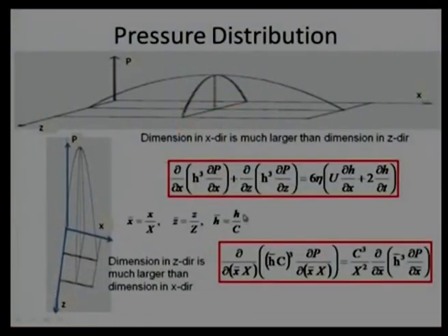To get meaningful results, we will also non-dimensionalize the film thickness. Say the film thickness is h; the non-dimensional film thickness, h bar, is the film thickness at any location divided by the clearance between the two surfaces, which is the mean clearance. If maximum or minimum values are given, we can average them out and get the results to some meaningful order.